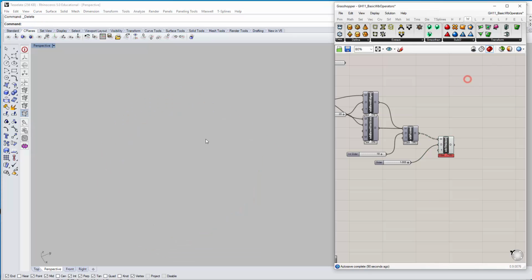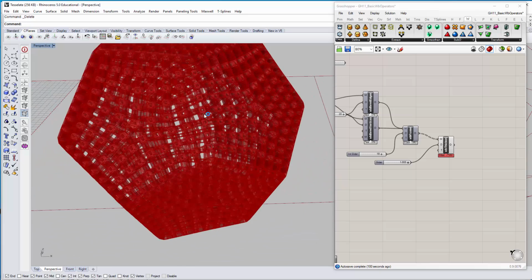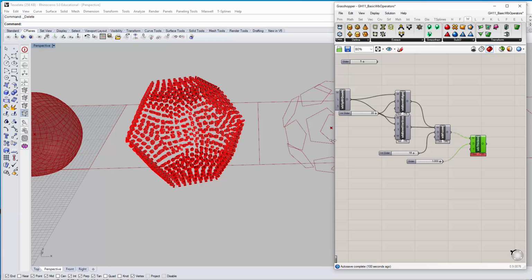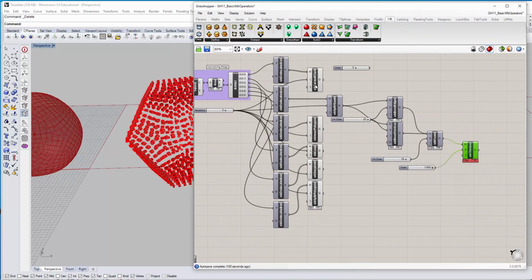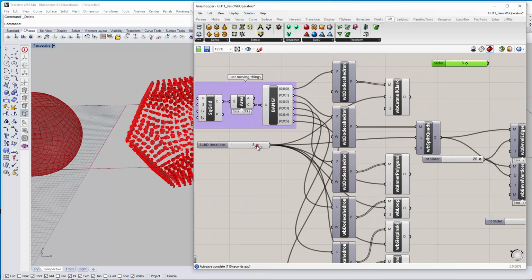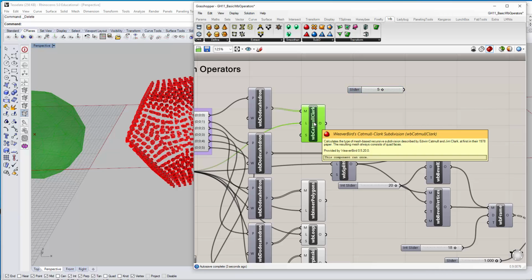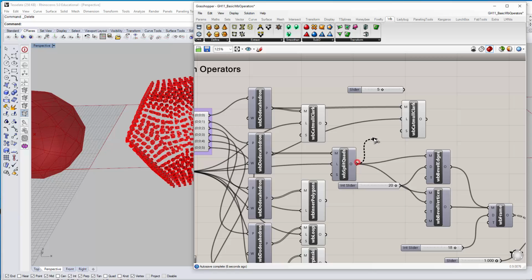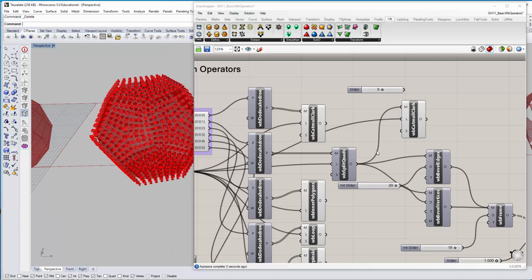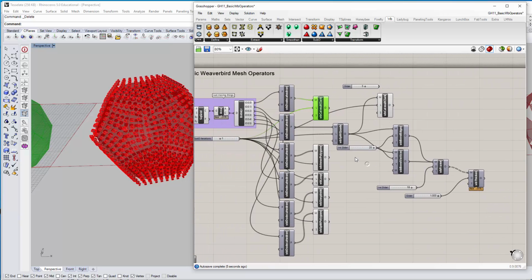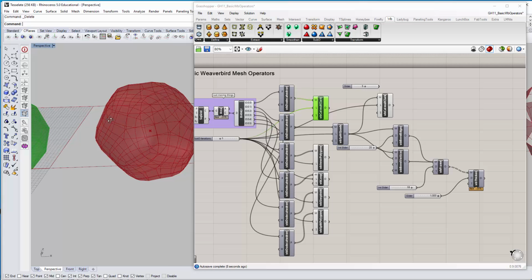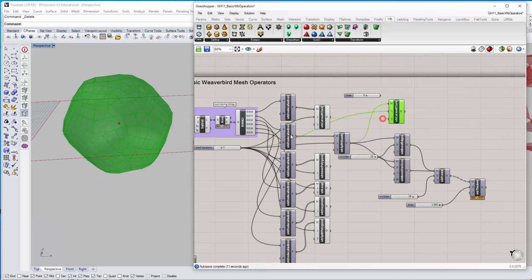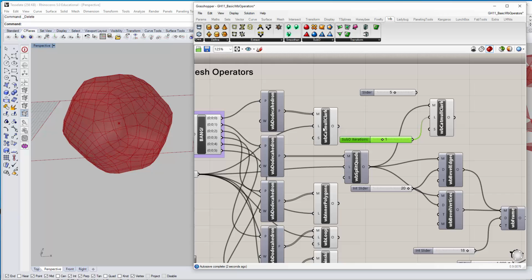Okay. Now, in particular, we're not stuck using only one of the subdivision modifiers by itself. You can just as easily mix and match them. So I could, for example, if I tone this down a little bit, copy the Catmull Clark and push the split quads into it, and I could just as easily do something like that. Let me delete this so it's not in the way. Okay. And let's do the subdivision iterations independently.